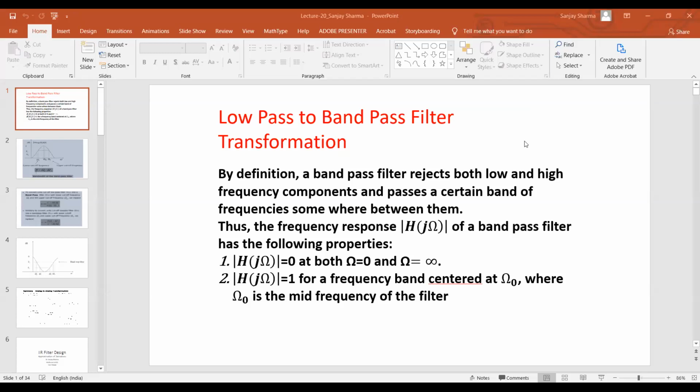So yesterday we were designing the Butterworth filters, and I have taken some examples also in which how to design a low pass filter. Designing a filter actually means to find out the order of the filter and the transfer function of the filter. And of course, we want to also know about the poles and zeros of the system, and thereby we can analyze the frequency response. So that's the whole crux of analyzing and designing a DSP system.